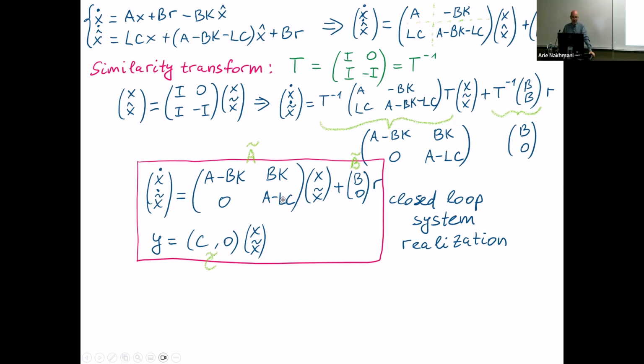And pay attention to how this equation looks. So this is x tilde dot equals (A minus LC) times x tilde plus 0. This is exactly the same equation as it was in open loop. So addition of controller, like I added now a controller, closed loop, it's not even there. The error is decaying to 0 exactly the same way with controller or without controller, in open loop and closed loop. Doesn't matter what u_k is, it's not even in the equation, right? It's not participating anywhere in here, right?